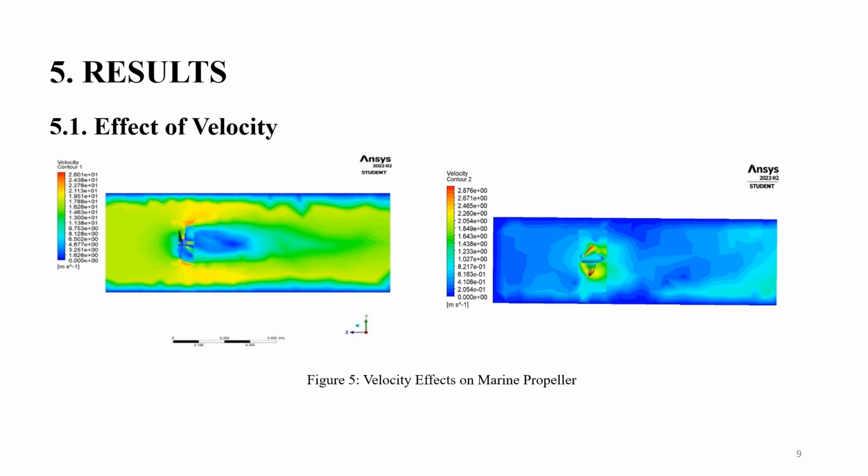So, examining the velocity contour illustrated in figure 7 reveals significant observations regarding the behavior of the propeller at a rotational speed of 900 rpm. Notably, the propeller experienced elevated velocity levels at the edge of its blades, a phenomenon attributed to the thrust generated by the propeller's rotation. Additionally, regions proximate to the rotating domain exhibit high velocity magnitudes.